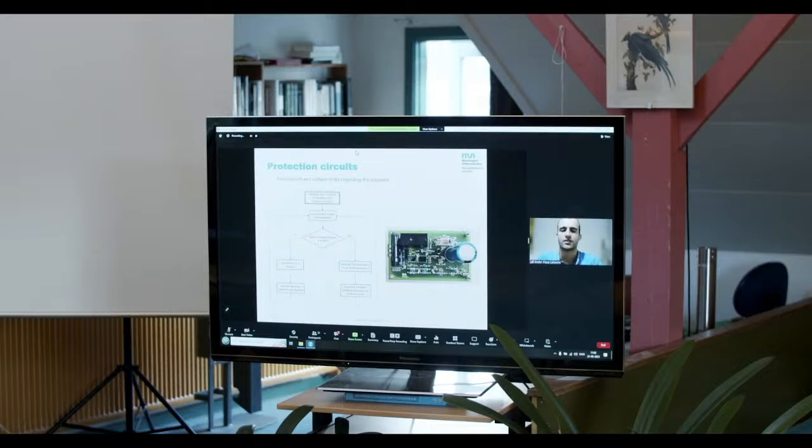In this part of the presentation, I'm going to talk about the protection circuits, specifically the protection circuits attached to the batteries which are charged by the aerogenerator. This protection circuit has two main functions: one is to protect the batteries from overcurrent, and the other is to supervise the voltage limits the battery has. It's important to mention that 3 different boards have been made, one for each battery that can be connected to the generator. These are 12 volts, 24 volts, and 36 volts respectively.